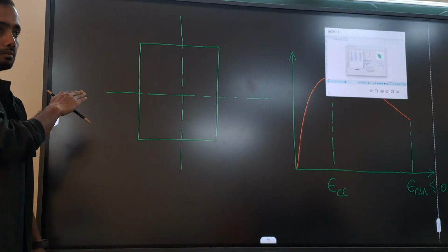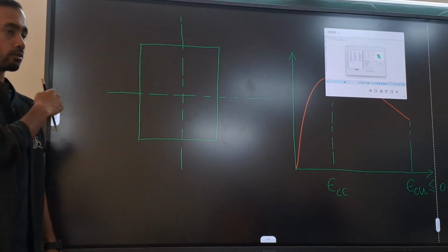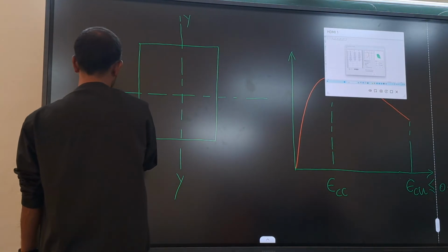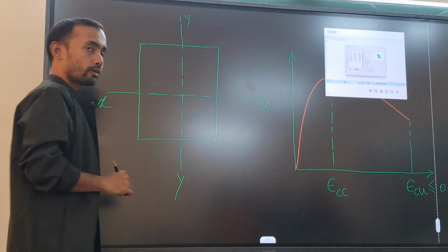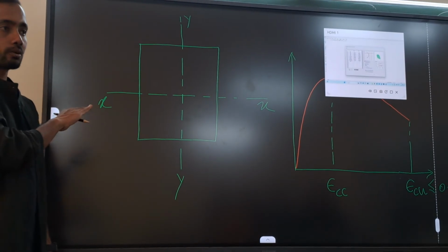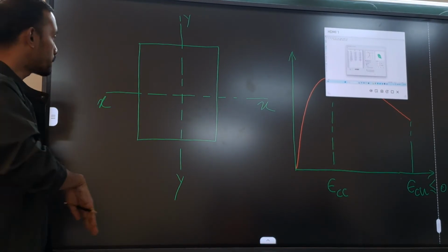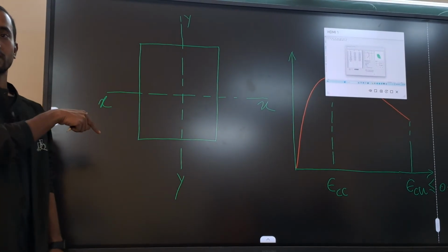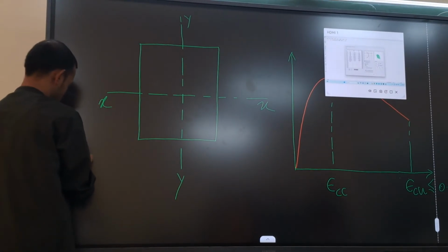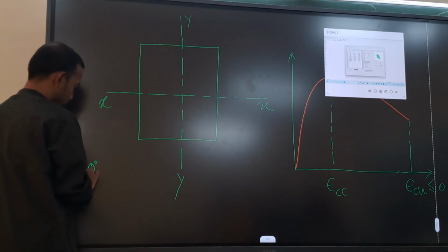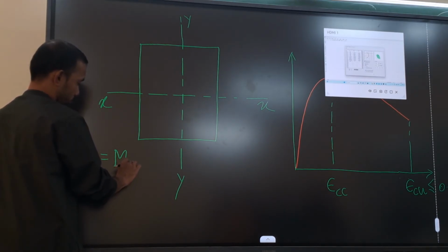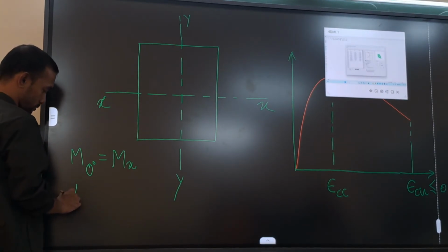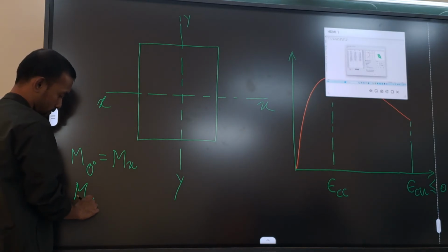See, normally this is the axis system you follow when you calculate the moment. Let's say this is the y-axis and this is x. So accordingly, you will have Mx, meaning moment about the x-axis, and My. Now, in terms of angle, if you want to represent this, x will be the 0 degree angle. So I can say 0 degree means Mx. Similarly, if I want to represent My, how much angle should I use? 90 degree.